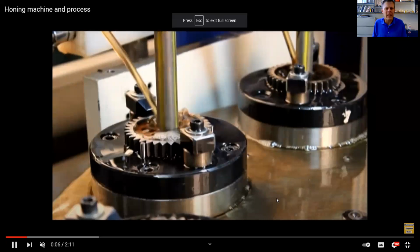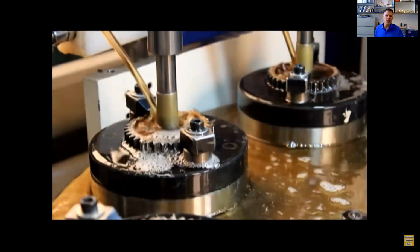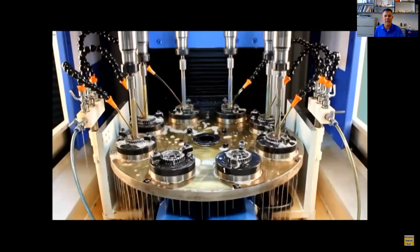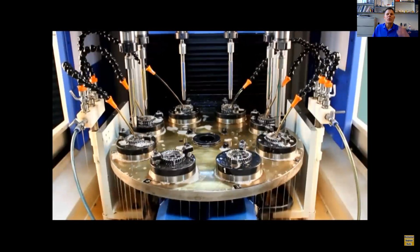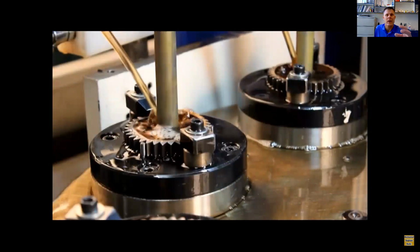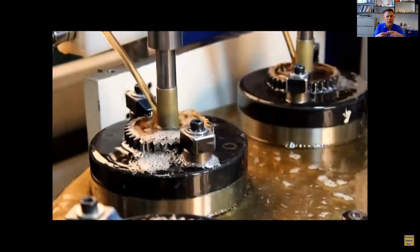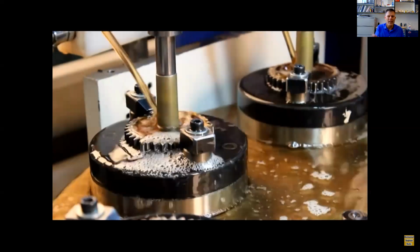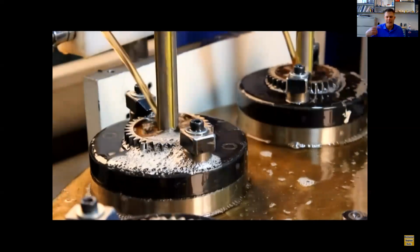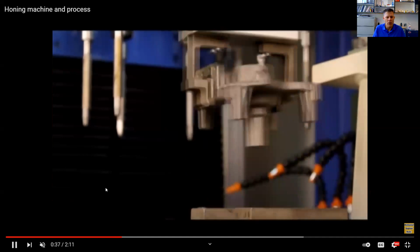So what they've got here, they've got a honing machine. So this machine is honing gears. Gears rotate on shafts, and you want them to last a long time in that transmission, whatever type of transmission they're going into. So you want a really good surface finish on that hardened surface of that gear in order for it not to wear out over time as it rotates over and over and over. So what they're doing here is they're honing the inside diameter of that gear to get that good surface finish, and so it can sit there and ride on the actual shaft. So that's what we got there with honing.